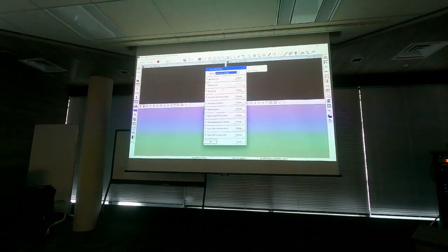If I choose Yellow Scan Voyager instead of DJI L1, nothing changes in here, but the macro that the software would create is slightly different. The software will have an estimate of the point-to-point noise level in the data, and that translates to a tolerance setting in some of the macro steps.